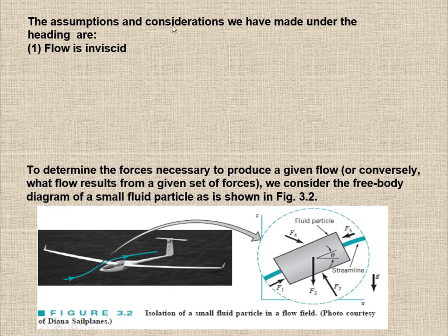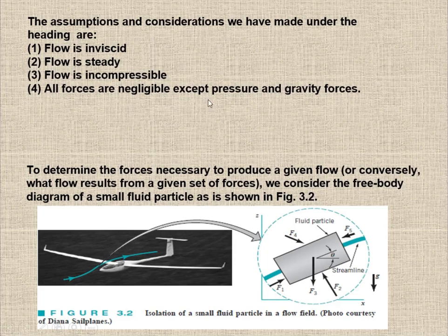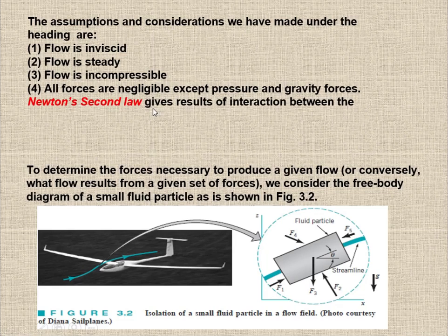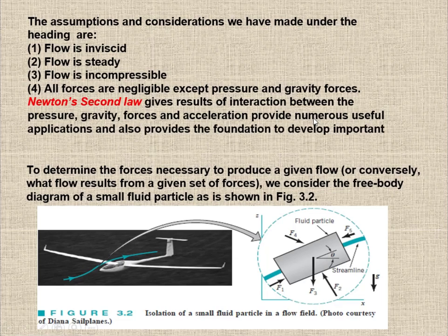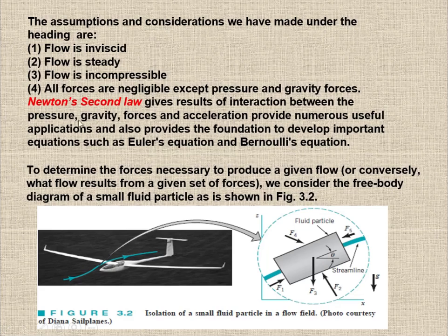So the assumptions and considerations we have made under the heading of Newton's second law are: the flow is inviscid, the flow is steady, the flow is incompressible, and all forces are negligible except pressure and gravity forces. So Newton's second law gives the results of the interaction between the pressure, gravity forces and acceleration, provides numerous useful applications, and also provides the foundation to develop important equations such as the Euler equation and the Bernoulli equation.